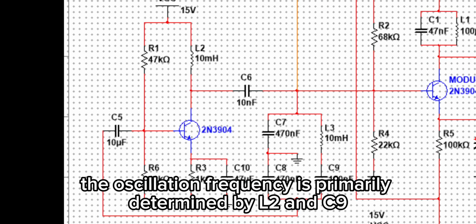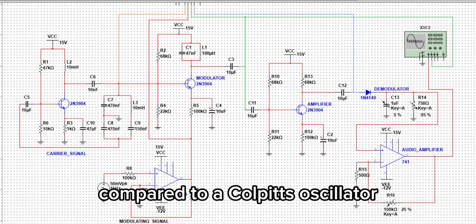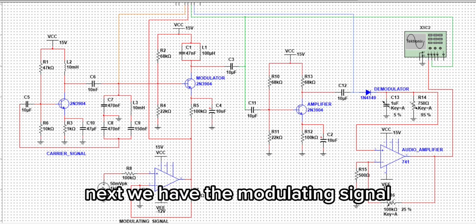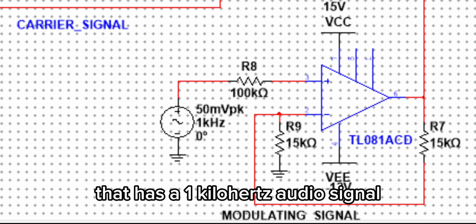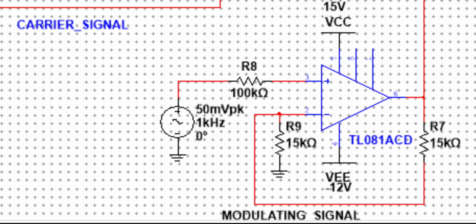The oscillation frequency is primarily determined by L2 and C9, making the frequency much more stable compared to a Colpitts oscillator. Next, we have the modulating signal that has a 1 kHz audio signal with a small amplitude of 50 millivolts peak to peak.